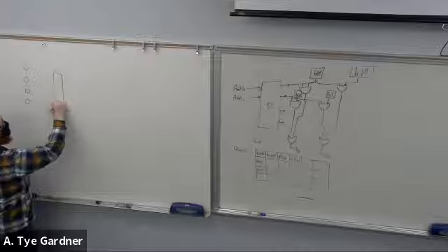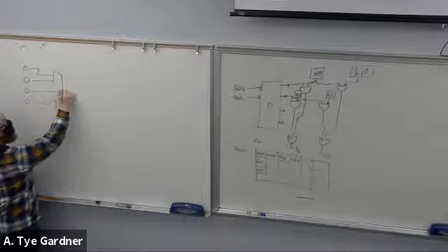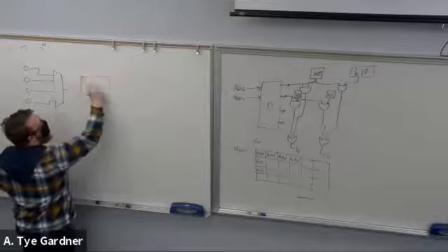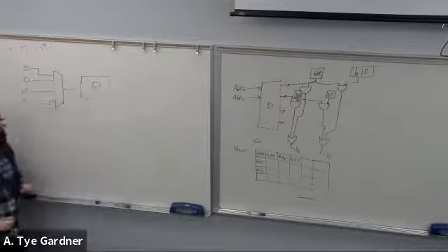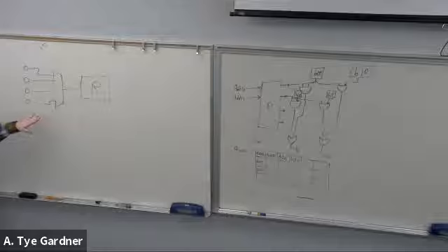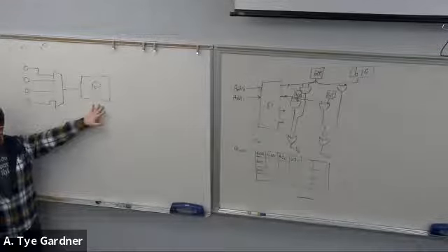You take a mux, you hook those electrodes up to a mux, and you hook the output up to, I'm just going to call this a block with an R for record. So now I can record any one of those 4 by just changing my mux channel, right? Same thing we've talked about using muxes before. It's just kind of in an analog sense, and it saves me a whole bunch of circuitry.